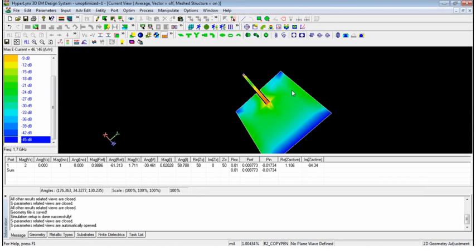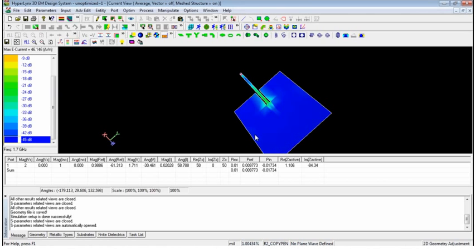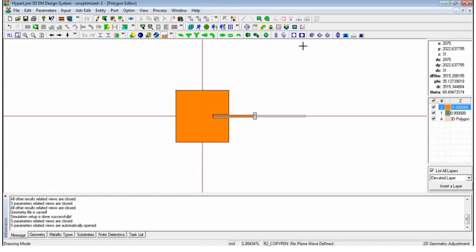You can animate it also. Whenever our source is excited in the antenna, it will show how exactly the antenna structure is excited and how the currents are flowing. Basically, if you see, the antenna radiates from its edges. Whenever the excitation is there, the charges accumulate at the edges of an antenna. So this is how optimization in IE3D works. Otherwise I can show you fast TM data also, where I can tune it manually and adjust the graphs.